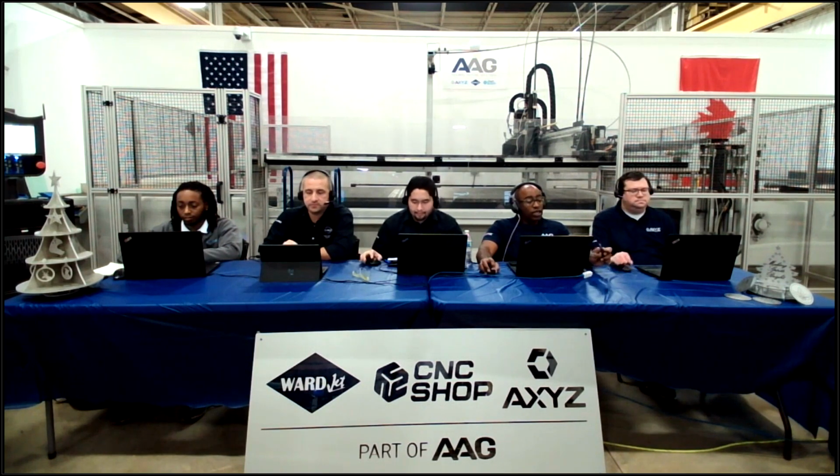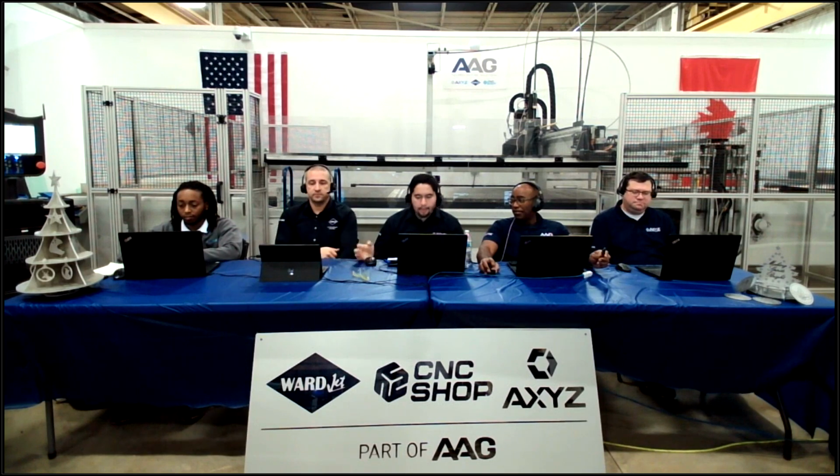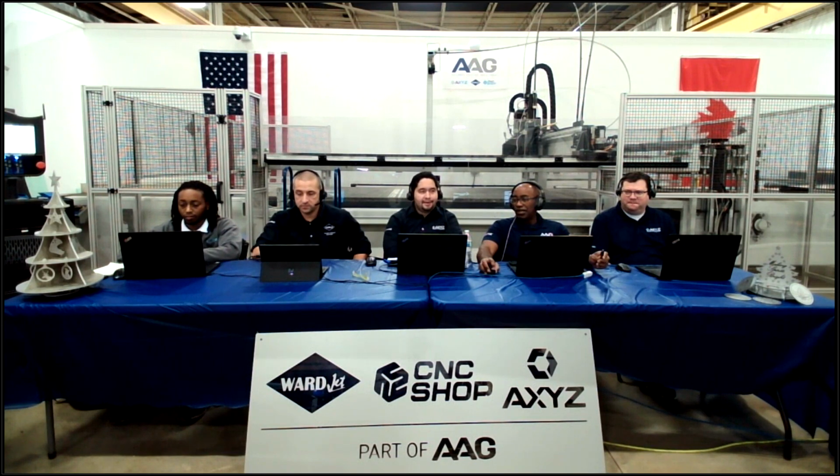Can you use a cold air gun system on an oscillating knife? You cannot, and though that's a pretty interesting idea, I could think of maybe a couple applications where this could fare well. But usually with the oscillating knife, we're looking at a very long, thin blade cutting into very thick material, and there is very little room for the air gun to blast and cool things down.